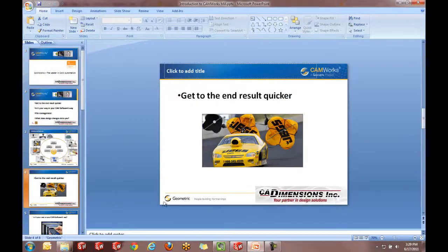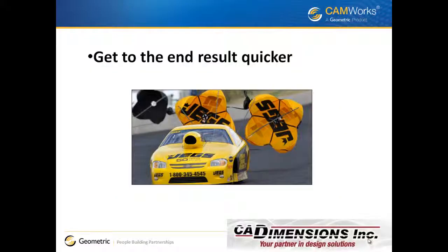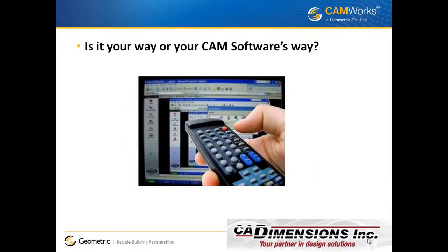All right, back to this one here. So you can see how quickly you can go in and do it just like you can in any other CAM package. You can change stuff, and you can pick stuff, and you got all the same options. But you can also see how quickly you have a head start on getting the product running. You could even take your roughing operations, quickly program them, and get them out on the machine. And while they're roughing, you can go in and tweak things on your finishing operation to be accurate.